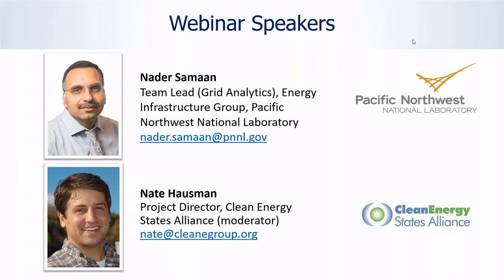Otherwise, they may get to the point where utilities simply say no, we can't allow your project to be connected without significant investment in our system. And as utilities ask for this capability, I think new projects will also ask the manufacturers of PV panel smart inverters to have this kind of capability. So it will evolve with time, and business as usual will not continue as the penetration level increases.